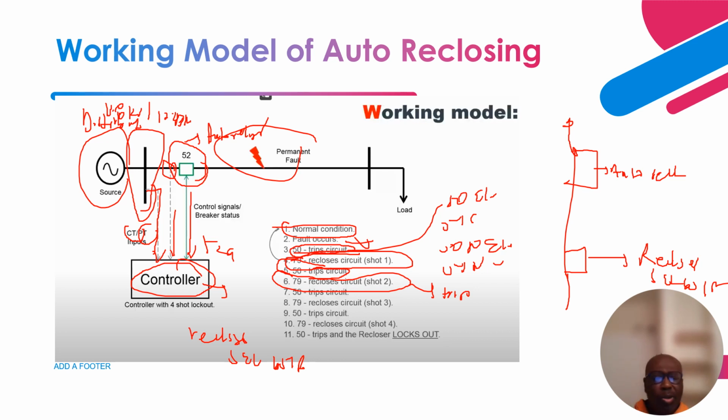Unless, of course, you have a dedicated customer for whom power quality is so important. The customer does not want any blips in their power quality, because when the auto reclosing action takes place, open and close, it causes a temporary dip in the power.